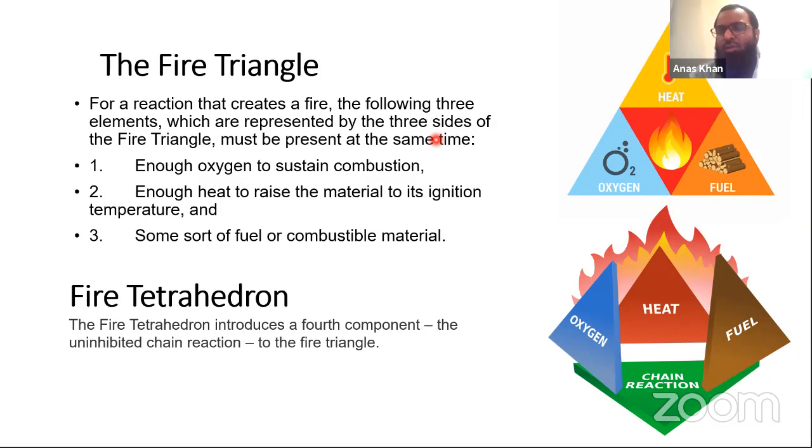Don't take the risk if you don't know what kind of fire it is and what kind of extinguisher or medium I have to use. The common saying is, when the fire is bigger than the size of a dustbin and you don't know how to extinguish it, leave it and call the emergency team or firefighting team, whoever is available in your home or in your industry.